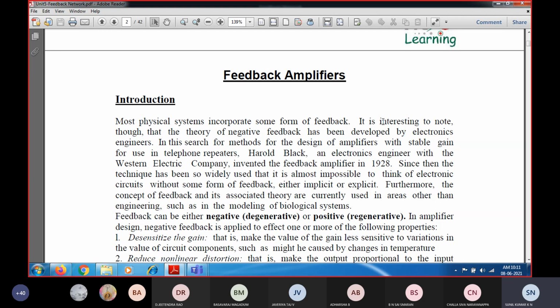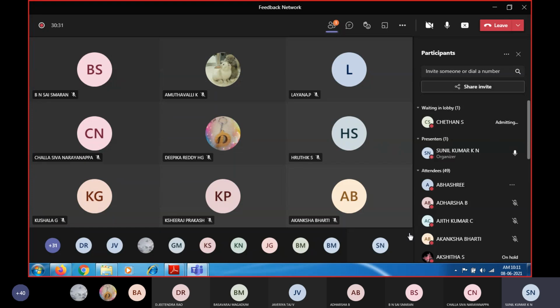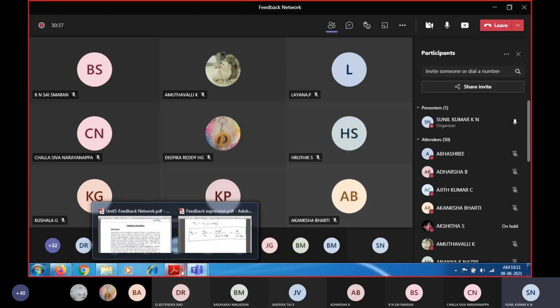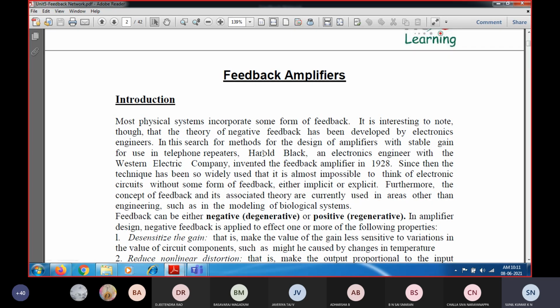So we can see that oscillators work with respect to positive feedback, and the positive feedback of the amplifier will cause sustained oscillation. At the same time, we have seen what conditions are to be satisfied, and what the loop gain should be for a given feedback. We have seen these parameters for both the RC phase shift oscillator and the LC tank circuit, and finally we have studied the concept of the crystal oscillator as well as the Pierce oscillator.